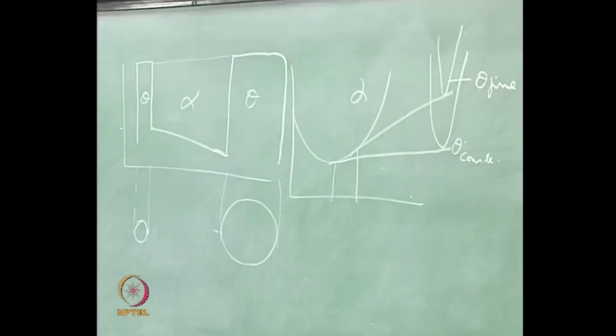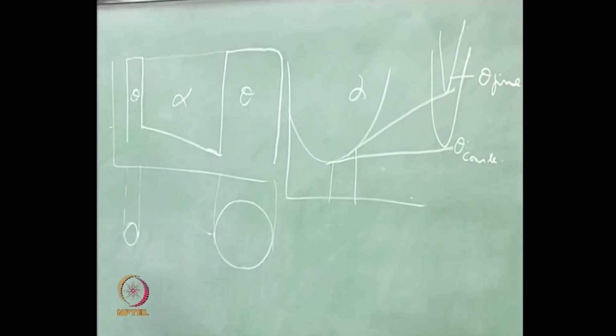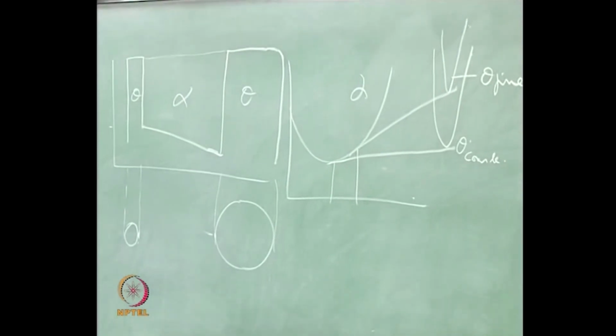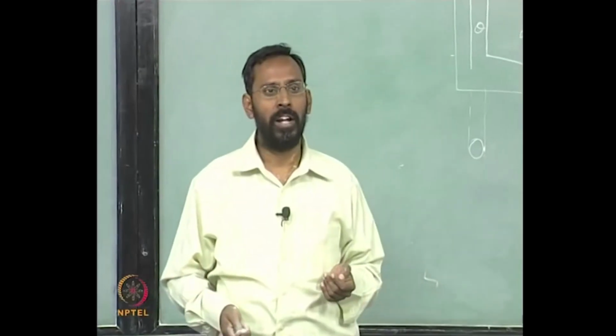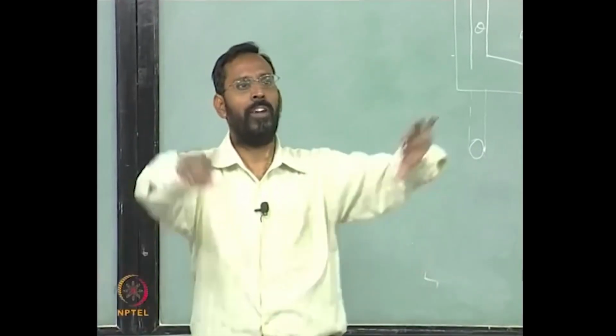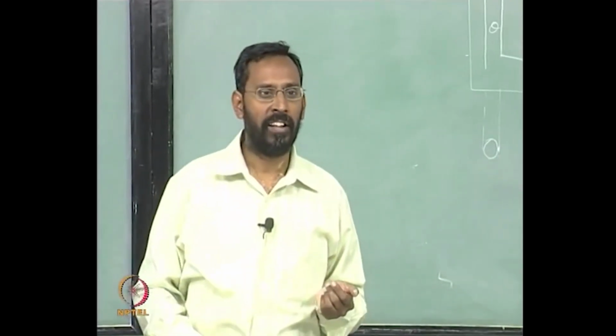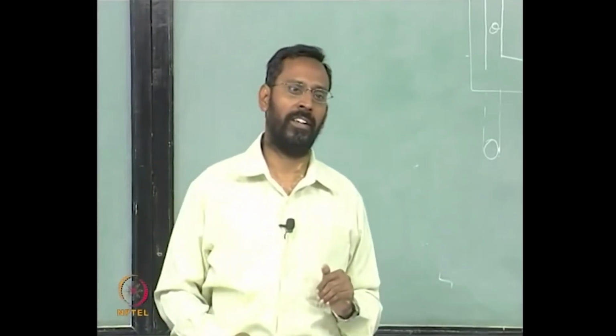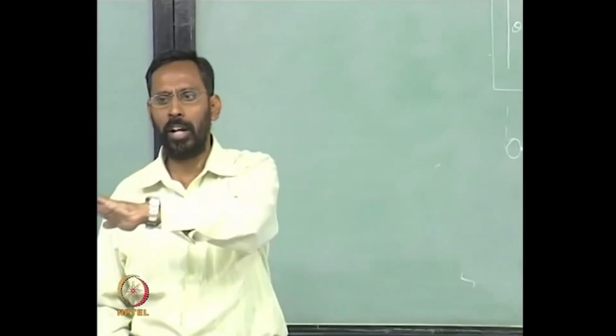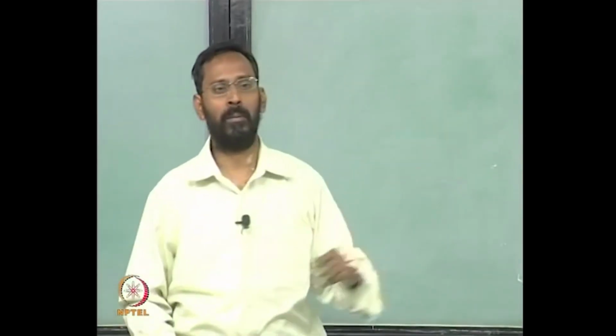Okay, dissolution of one precipitate and growth of another precipitate is not possible. Only thing is, ideally, if all precipitation has occurred at the same time, and if it is a homogeneous precipitation, not a heterogeneous precipitation, then in principle nuclei have formed everywhere. This is what we call the site saturation case, where there is no more nucleation taking place. At time t equal to 0, all the nucleation has taken place and all of them are trying to grow. When they are trying to grow, you get into this problem.